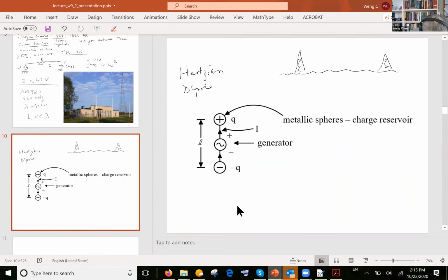They're still much smaller than the wavelength, okay? And then you have a ground, and the effective permittivity of a conductive medium, does anybody remember what that is now? Is something like epsilon complex is epsilon minus jσ over ω, right? Remember that I can model the ground with an effective permittivity or complex permittivity.